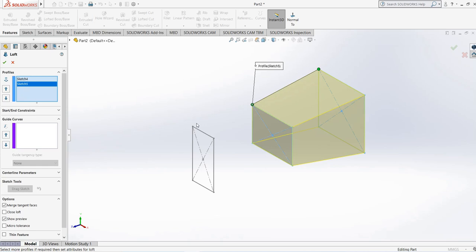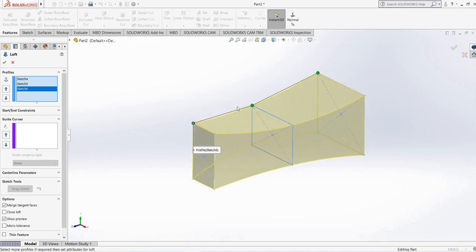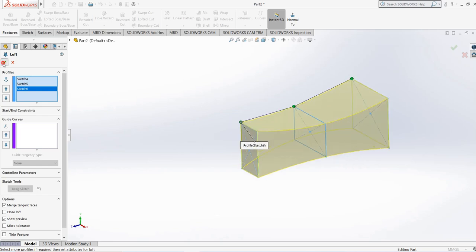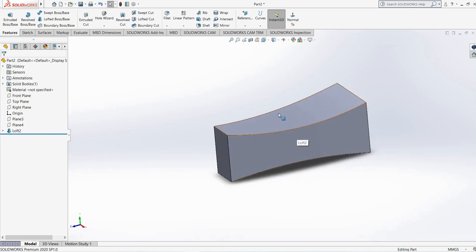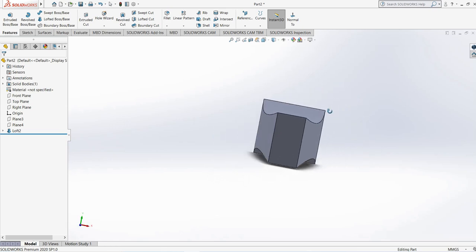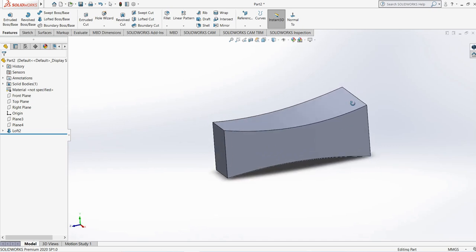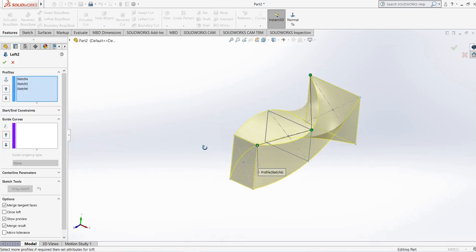But what will happen if we select this sketch 6? I will select this one, and you can see it smoothly joins all these profiles or all the sketches. Okay, when we complete it, it will look like this. So this is how loft works. So we have different geometries: the middle one is different, with more width or more length, and this one is different. So we have this type of structure, and we can also edit it and change the structure like this or this, right?